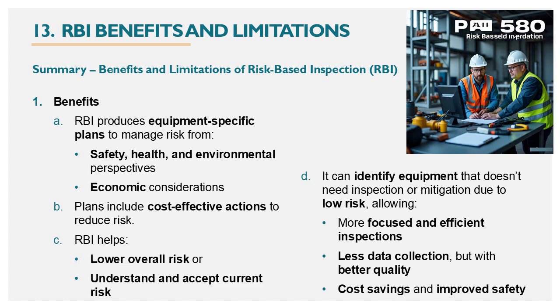perspectives, and also economic considerations. The second benefit is plans include cost-effective actions to reduce risk. The third benefit is RBI helps lower overall risk score. Understand and accept current risk. And the fourth benefit is it can identify equipment that doesn't need inspection or mitigation due to low risk, allowing more focused and efficient inspections, less data collection but with better quality, and cost savings and improved safety.